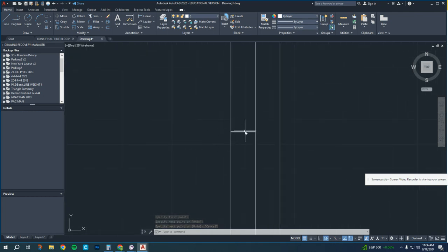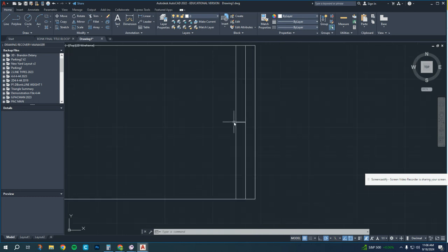But that's how you draw that in exactly the middle of these lines. You just find the midpoint with that midpoint snap cursor option, it's called. All right, now we need lines to split this into threes, and we're going to use the bottom and top lines to make copies and offsets, and you'll see that it's a little bit different here.